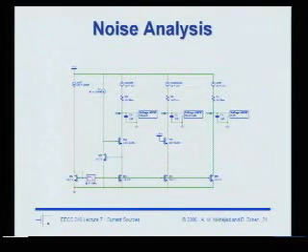Here's a noise analysis of the three circuits. So again, noise analysis of the regular mirror, cascode mirror, and then this gain boosted. And what happened to the gain boosting? So instead of using an amplifier, I'm using an explicit transistor, right? The simplest gain booster is just a single transistor. Takes the voltage here, boosts it up. It has gain because of this current source. And so this is the world's simplest gain booster, which in fact turns out to be a shunt feedback pair.